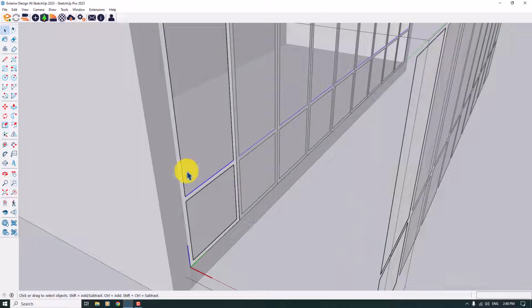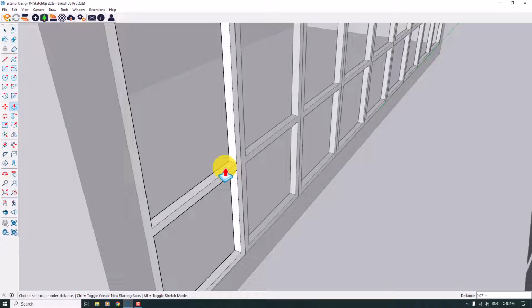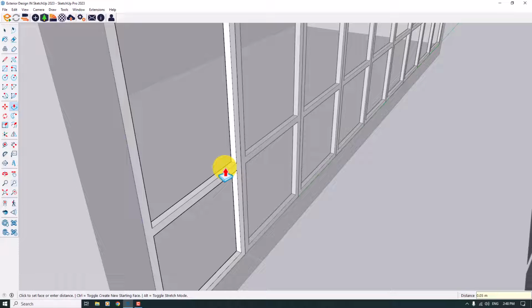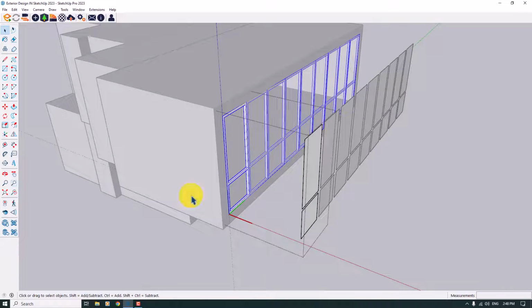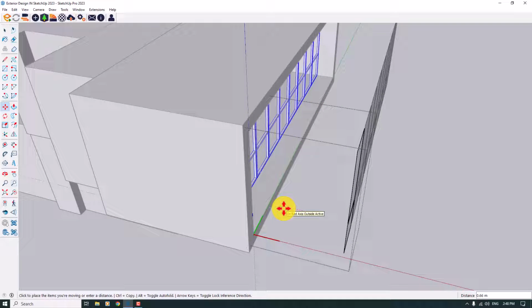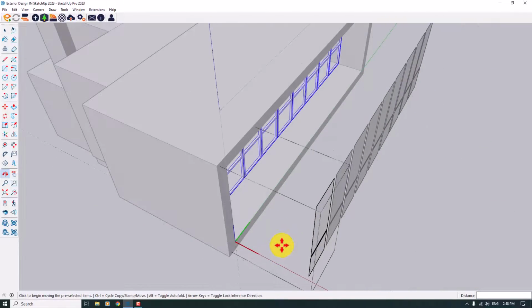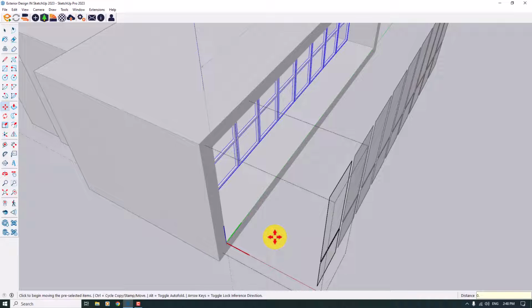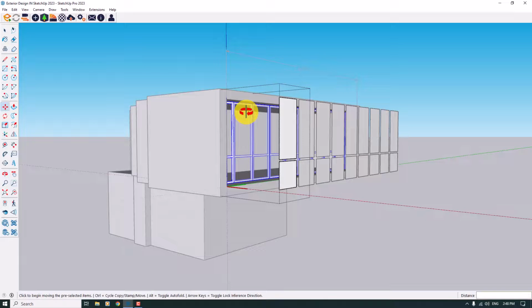I want to start my job with the frames in here, so I will extrude them to the backside with some number about 5 centimeter, 0.05 meter, and I will click on it, convert it to a group another time, and move all of them at the same time on the red axis, about maybe 1 meter, something like that. It is really wonderful in detailing. So SketchUp can create some immersive 3D models for you and your project.